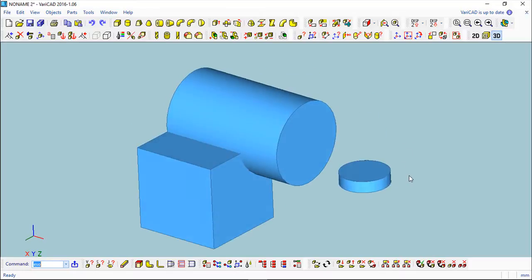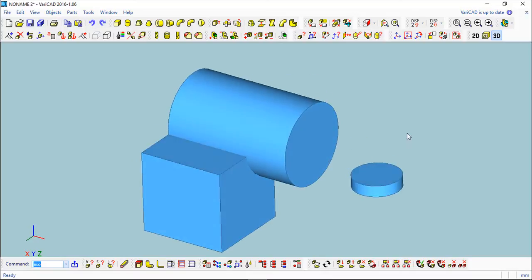The advantage of creating by this method directly on the 3D is that if you need to edit later the solids or these basic profiles, then they will be edited in the same place where they were created, which is quite convenient, instead of having this creation done on the 2D that in fact has no connection with the solid.